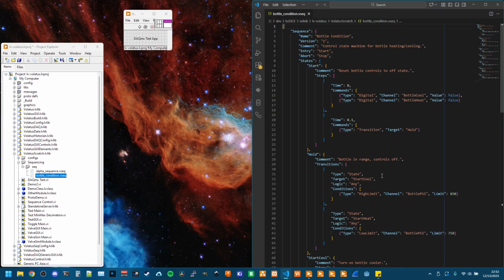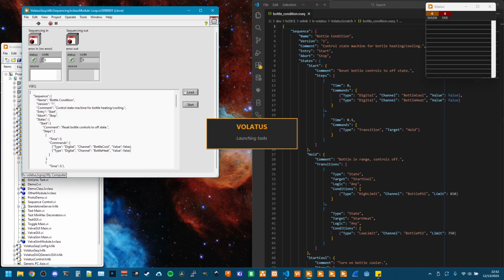Pretty flexible system. Currently, I've got it hard coded at a 100 hertz loop rate, and that'll be a little bit configurable in the future. But I'm mainly intending for this to run on cRIOs at the moment, so that's my first target. And this is going to run GSE for rocket engine test stands and structure test stands down the road. But I've got this right now. I don't have all of the communication up for making this work, so I'm doing it manually in the GUI.